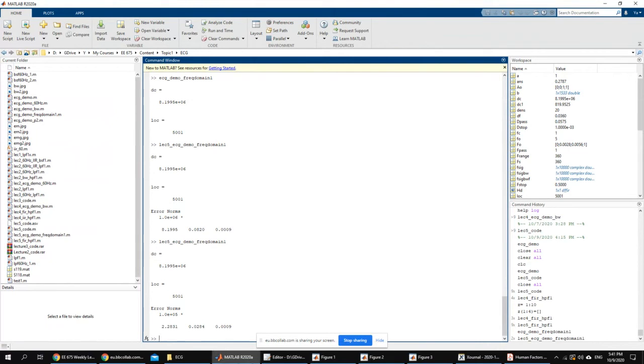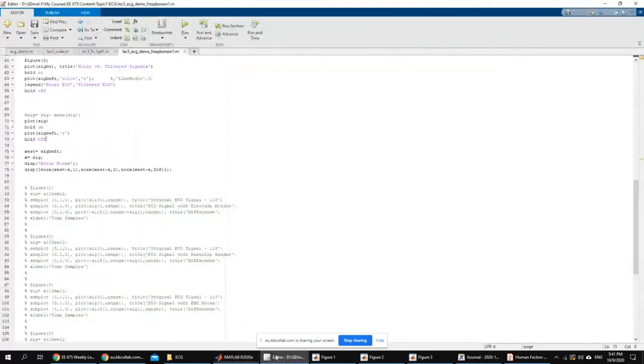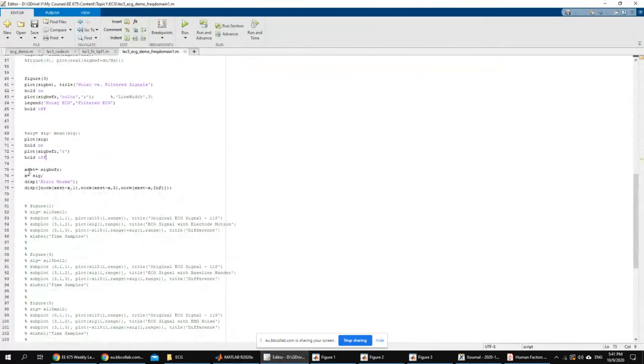So the way you compute the error in all filtration methods, whether they are FIR, IIR, or frequency domain, is exactly the same. You just put X estimate as the filtered signal, X is the original signal, and just compute the norm. That's it. You have the choice of which norm to use.